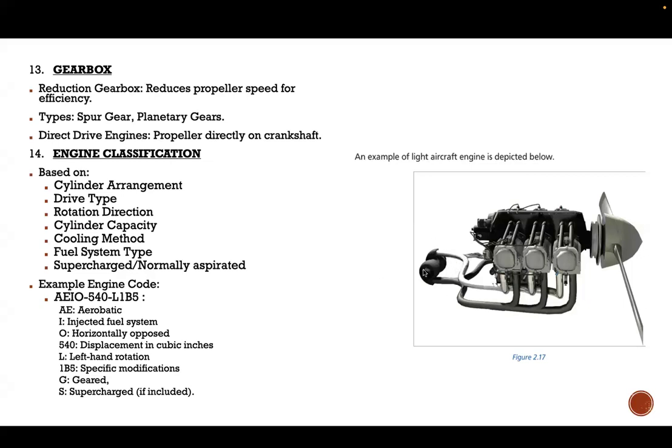This part that you see at the back of this engine is called a turbocharger. We'll explain this later when we come to that particular chapter, what a turbocharger is. But in short, it uses exhaust gas to spin a turbine, which spins a compressor, which is going to compress some amount of gas already. This compressed gas then flows into your intake manifold and goes into your engine.